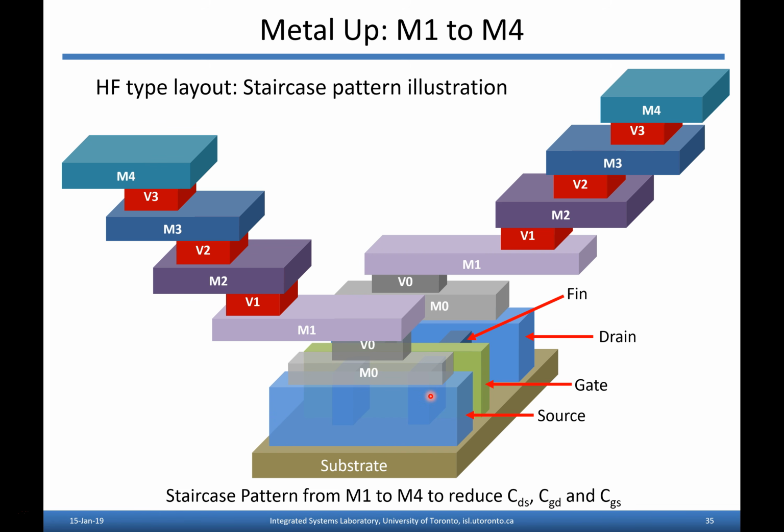Again, some of these tricks may work in one technology, and then you go to a different technology and some different set of design rules kick in and you're just unable to adopt that style of contacting the transistor, and you have to totally try something different. So all these complications, I should say, seem to increase the time required to do layout with FinFETs by quite a factor, like a factor of 3 or more, right? It just takes way longer to lay anything out and make it DRC clean because of all these considerations.